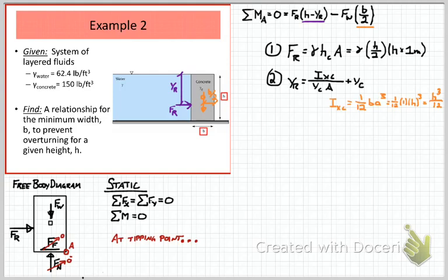The depth is h cubed, and so that moment of inertia can be termed h cubed over 12. We also need to know y to the centroid. That's the distance measured along the plane to the centroid, and that turns out to be h over 2. Now, making those substitutions back into our equation, we see that the resultant force acts 2/3 of the way down.